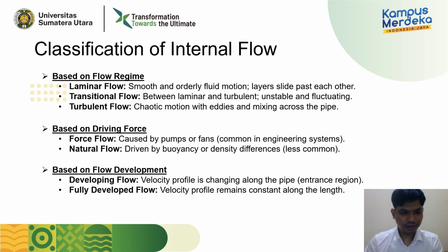And the last classification is based on flow development. Especially if we talk about pipe flow, we're going to talk about two kinds of flow development. The first one is developing flow, where the velocity profile is changing along the pipe. We also call it the entrance region.